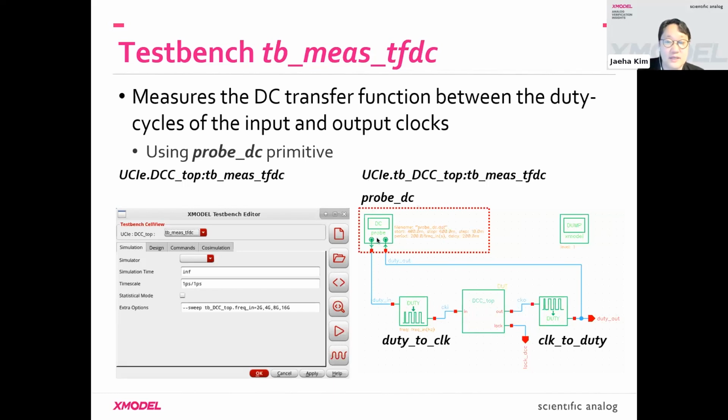What this one does is generate an input stimulus that will gradually change over time, in a fashion that's slow enough so that the input can be regarded as DC. At the same time, it measures the response of your circuit while making that change, collects all the input and output values, and builds a table.